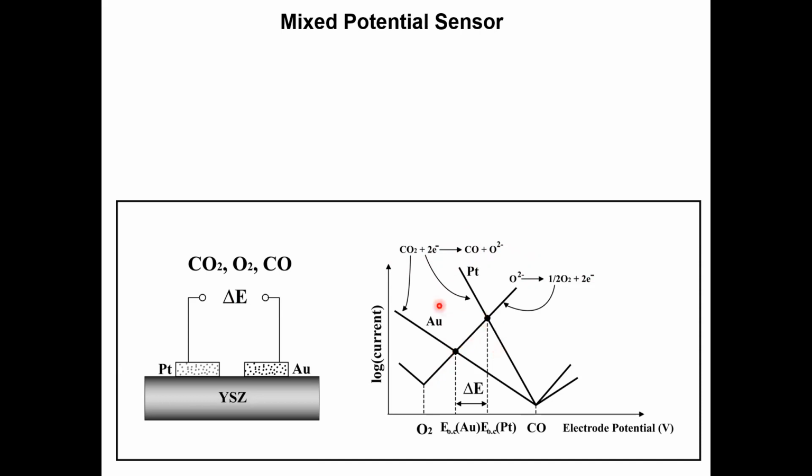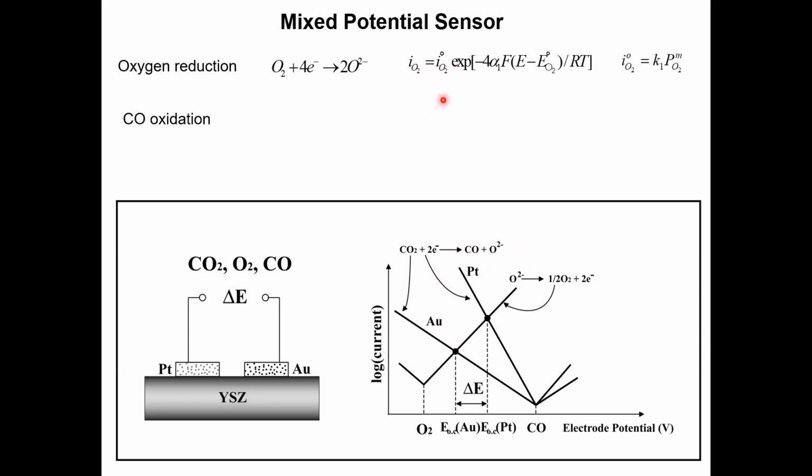And the idea now is that on a sensor like this, you can see some detail: the oxygen reduction reaction will lead to this oxygen reduction current, and the CO oxidation rate will generate the CO oxidation current that you're measuring and plotting in here. But the beauty of this is that you can change your electrode. So let's say I put rhodium or some high temperature oxide catalyst material that will change the CO oxidation reaction, meaning that it will change the slope.